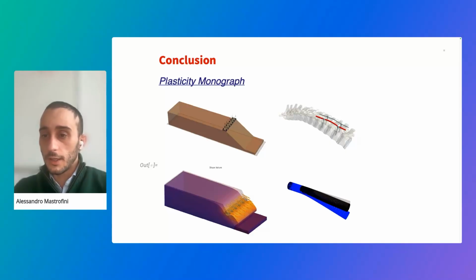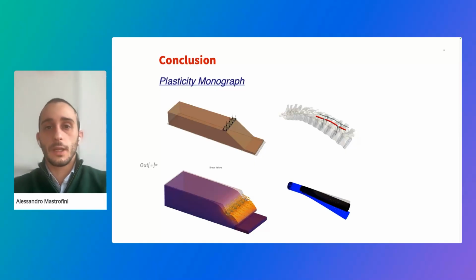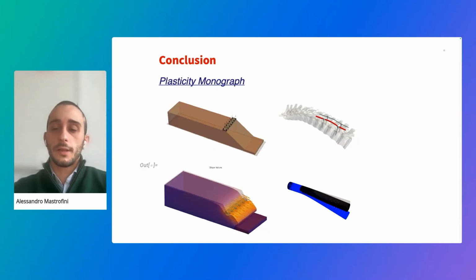It's important to specify a non-associated plastic flow. In some mechanics, associated plastic flow can give unrealistic dilatation, which can impact the results by inflating confining pressure. Yes, that's true. I don't think in this version it may be possible.